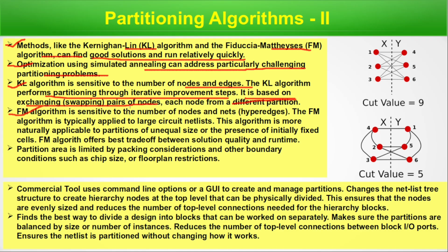The FM algorithm is sensitive to the number of nodes and nets, or hyperedges. The FM algorithm is typically applied to large circuit netlists. The algorithm is more naturally applicable to partitions of unequal size or the presence of initially fixed cells. The FM algorithm offers the best trade-off between solution quality and runtime.